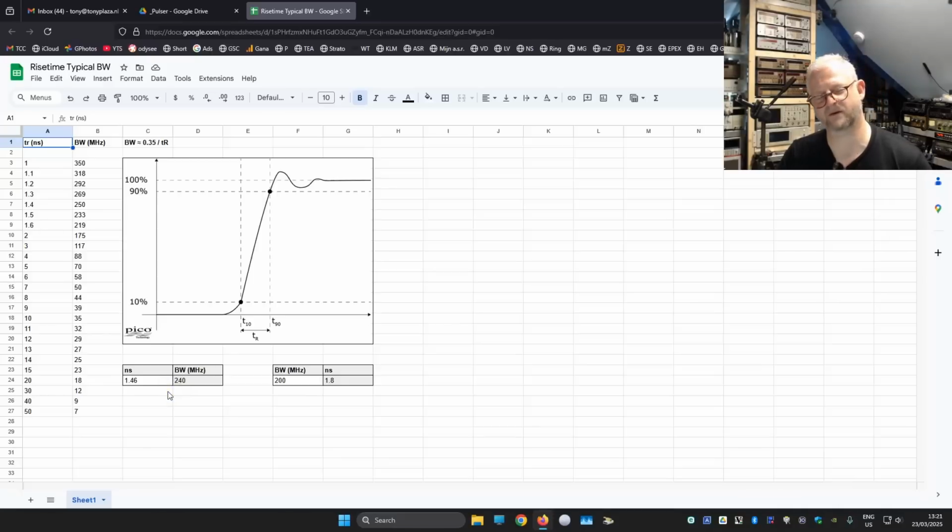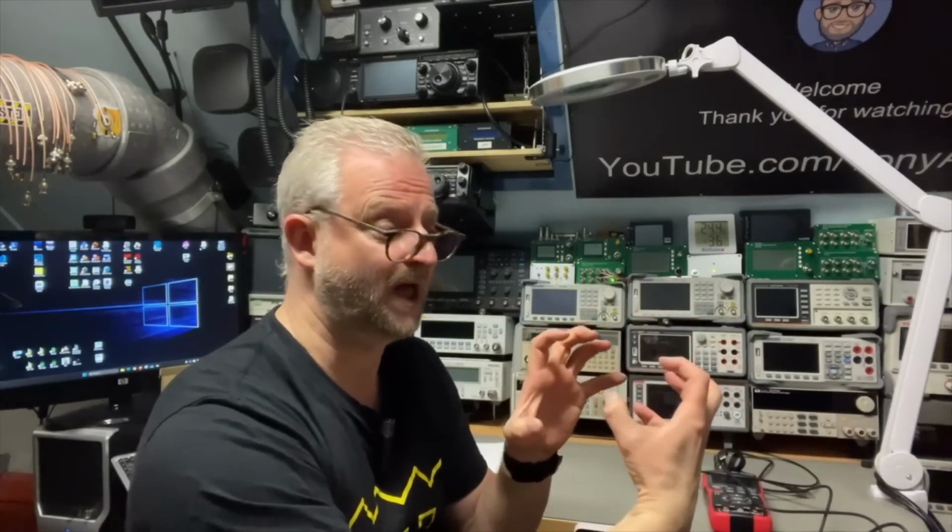But we already saw on the practical side that it is actually not the case, because we couldn't really zoom in because the time base was the limit here. So this was a nice example why it is an added value that you can change it from 1 megahertz to 10 megahertz or the other way around, and you can even do it from a few K all the way up to 300 megahertz. If you use TDR, so the time domain reflection, so if you want to measure the length of the cable based on the reflection of the signal, then depending on the length of the cable, you want to be able to change the frequency.